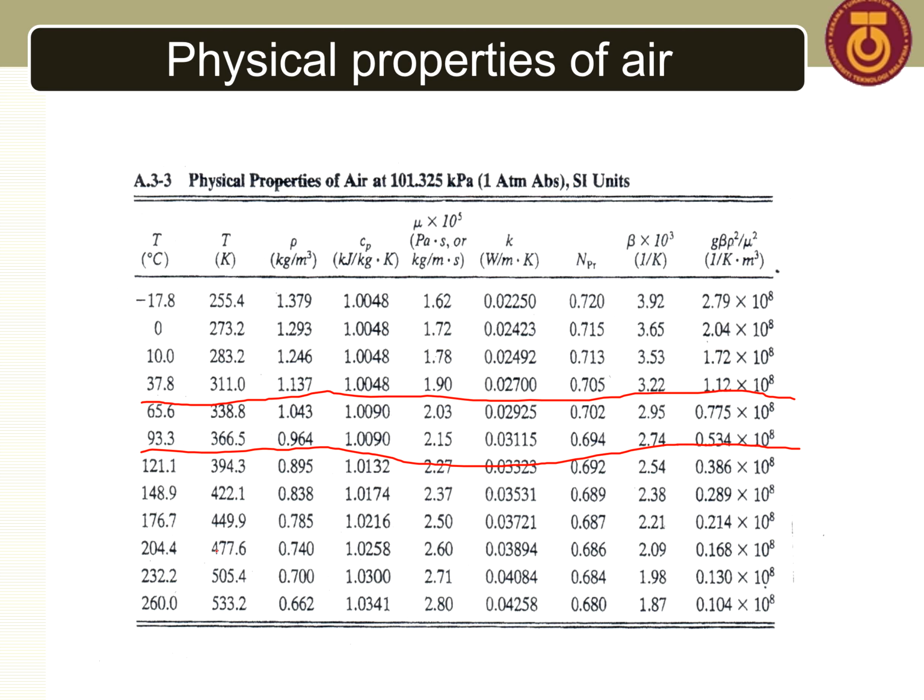Okay, so for the rest of the properties, which are density and heat capacity: the heat capacity here is in kilojoule per kilogram Kelvin. If you want to calculate the Reynolds number, of course you should multiply by 1000. So instead of 1.009, you should take 1009, in joule per kilogram Kelvin.